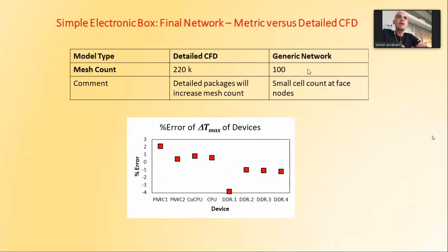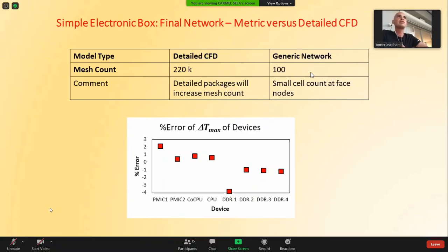Okay, so the disadvantage is that you cannot work outside of the range of validity. The advantage is that you can always have another verification point added to the generic network. You need to check, because you're talking about fans and flows, some important things that we will not go into, that you don't have something like bifurcations inside the simulation.